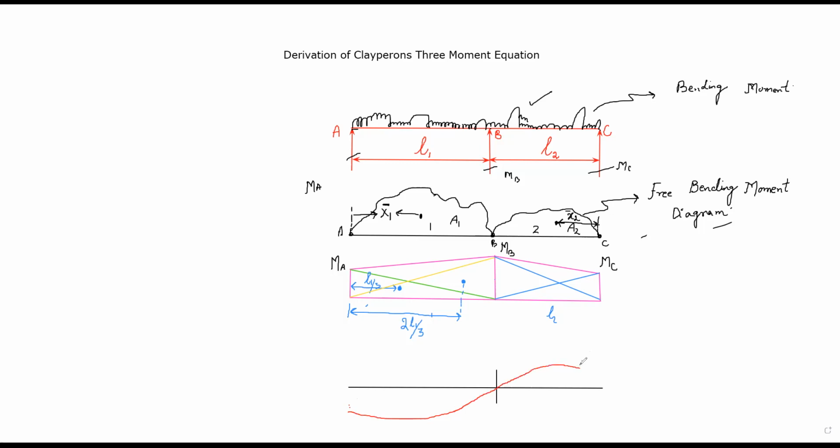Let's suppose this is how the deflection curve looks. Now the question is why we are showing the curve concave here and convex here. The reason is you are essentially having a support over here. So what will happen? This load will move. If this load is moved, then this will deflect downwards, but this will deflect in the upward direction. Okay, that's quite evident.